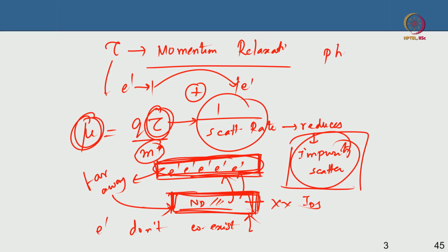However, phonon scattering will always be there, and that is unavoidable. Phonon scattering basically means that at any given temperature the atoms will vibrate like a spring, you can say. They can vibrate in phase, out of phase, transverse, longitudinal, etc. Phonon scattering is the atomic vibration that will scatter the electron, with a potential that they set up at any given temperature above 0 Kelvin.